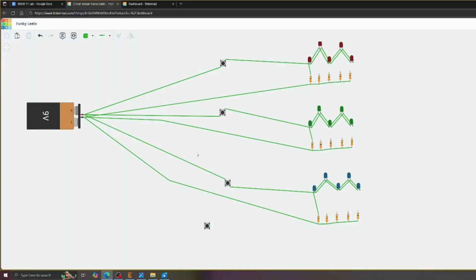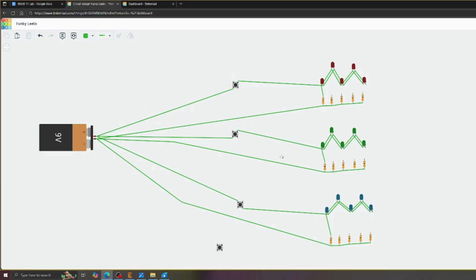Okay, so now we're back, and we have all of our LEDs connected the same way we did to the first LED, the red row. So just to recall, just in case my first time wasn't that clear, we always connect our positive terminal to one of the first terminals in our button. And remember, the button works diagonally. So if you choose 1B, you have to connect your other side to 2A. If you choose 1A, you have to connect it to terminal 2B.